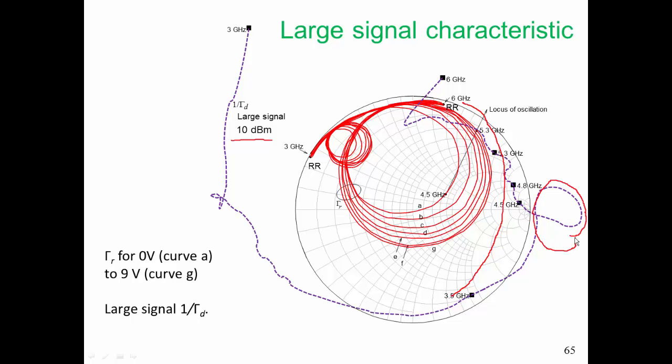So we see some other effects here. We see some wobbling around. In fact, we see a little loop here which indicates some resonance. Perhaps that resonance was introduced by the very measurement fixturing that we had to employ. I kind of doubt that that resonance is going to be in our active network anyway. And besides, this oscillator works, and it has really good characteristics, and it can be tuned over the full tuning range, which makes me even feel more confident that that loop is spurious.